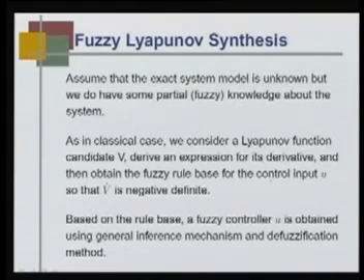So, the objective here is that we prescribe a Lyapunov function for the system, find the rate derivative of this Lyapunov function, and substitute the dynamics of the system in it. Now we create a rule base in such a way that this Lyapunov function derivative is qualitatively negative definite, not quantitatively.